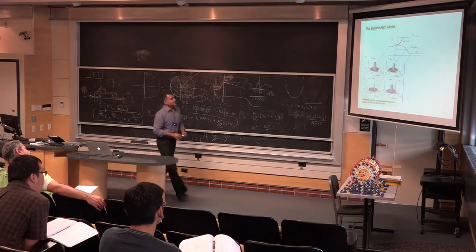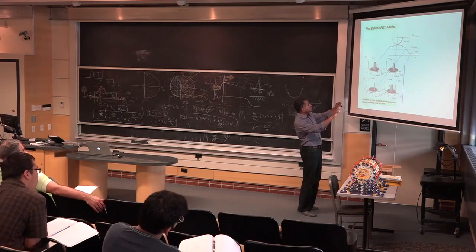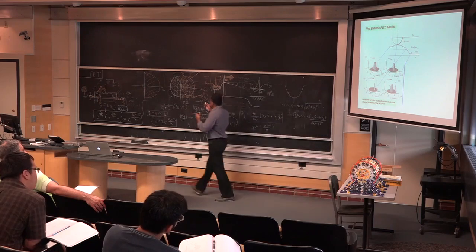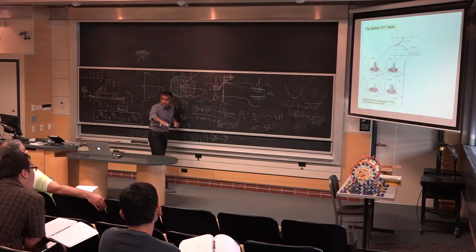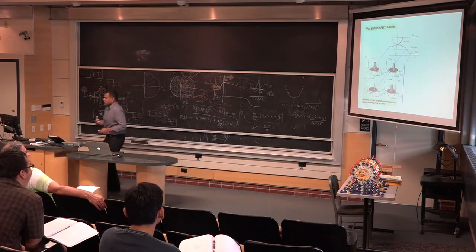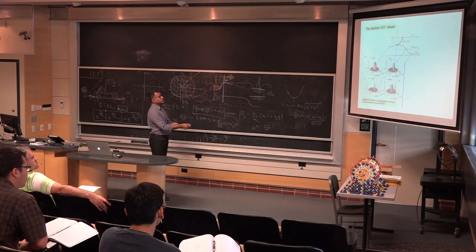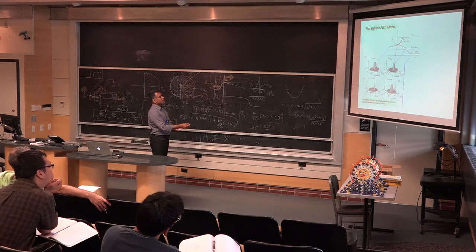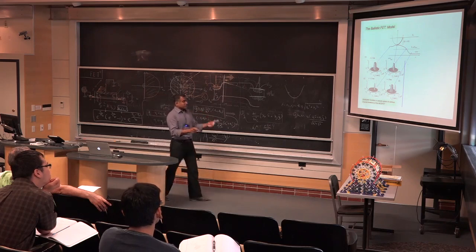Here are some nice pictures of what I was just trying to claim. So this is now in 2-dimensional space, kx, ky. When I'm drawing circles, you realize that the Fermi-Dirac distribution is 1 when the argument is very low, and then it goes through a step, and then it has a tail and all that. So the surfaces are not as sharp, but what we are getting is an exact expression now. And here, for example, out in the source, we are looking at the right-going carriers. At the source injection point, it pretty much looks like all carriers, at a reasonably large drain voltage, are moving to the right. It's a two-dimensional k-space now.